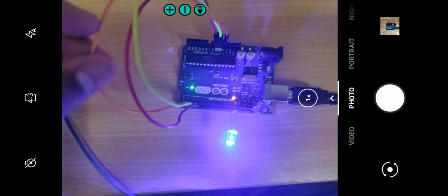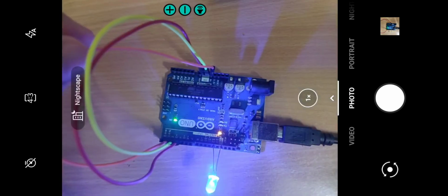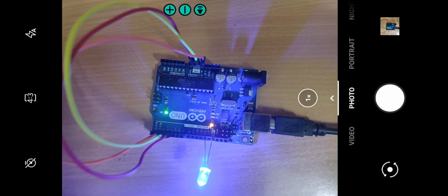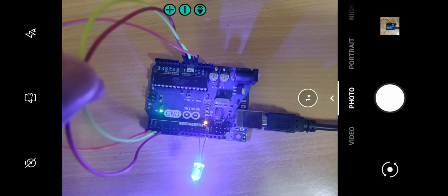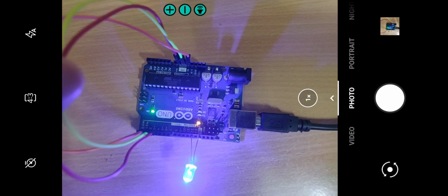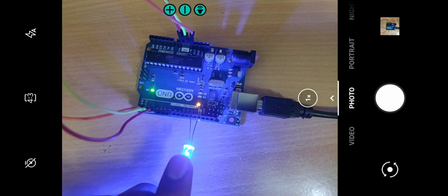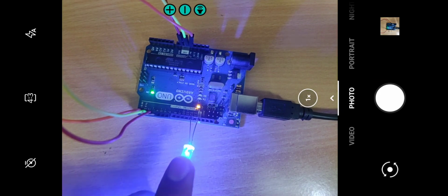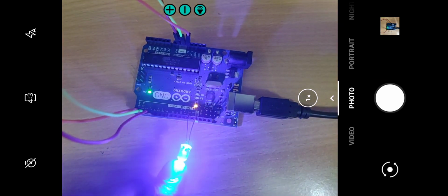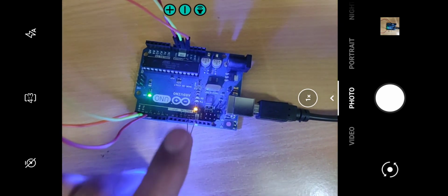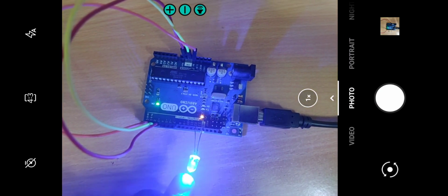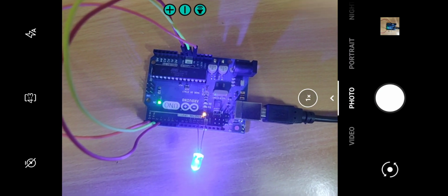So now A is connected to the orange wire. A is connected to 5 volt, which is 1, and B and C are connected to ground, which is 0. So we are giving 1 0 0 as the input, and as per the truth table we are getting 1 as the output. So for NAND output we are getting 1, as well as for KMAP minimized expression we are getting 1, the inbuilt LED. So this verifies the truth table and the output obtained in the assignment 1. Thank you very much.